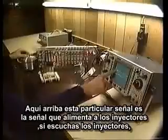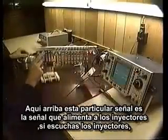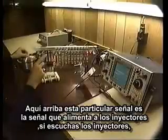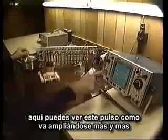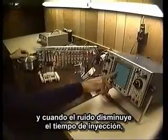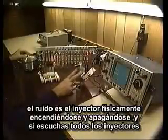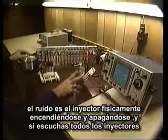Up here, this particular signal is the signal that's fed into the injectors. If you listen to the injectors, you will hear and see that this pulse width gets larger and larger. What this pulse is, as I'm decreasing it, would decrease the injector time. And the clicking that you hear is the physical injector turning on and off.